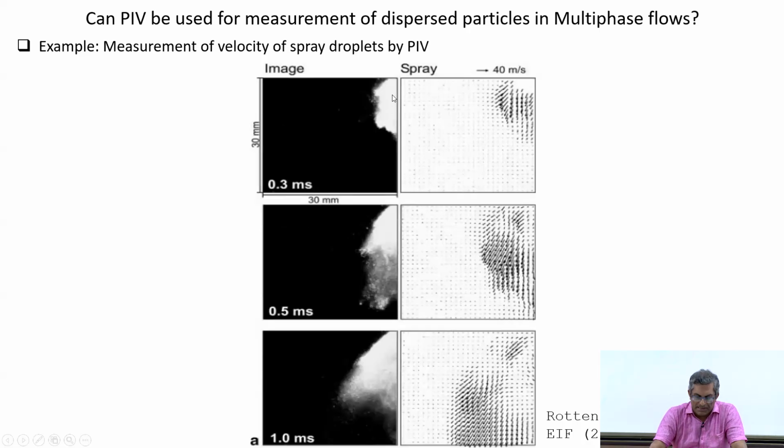Basically the spray is injected using an injector which pressurizes the liquid to high pressure and then injects the pressurized liquid into ambience. That is how they have captured the images. And now, these authors have performed PIV measurements over this. You see you get the velocity vectors, but what is the difference with respect to the previous PIV measurements that I had shown, or what we have discussed?